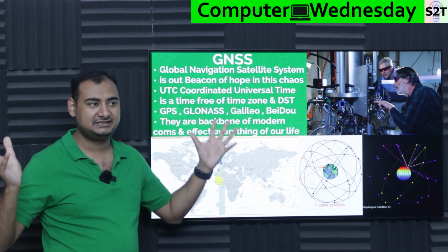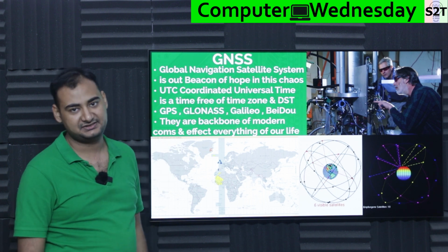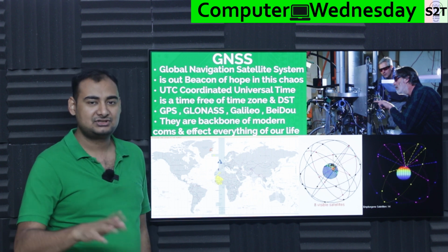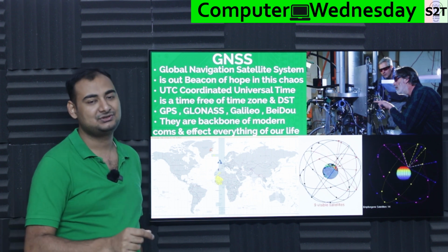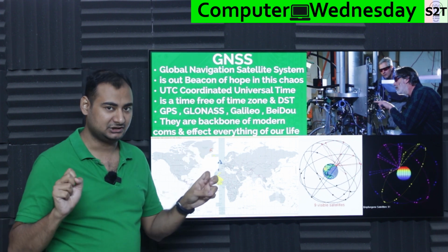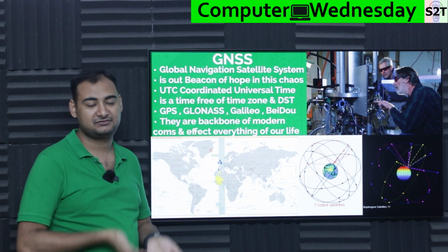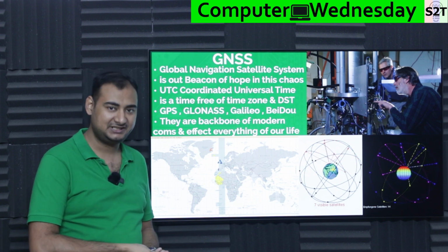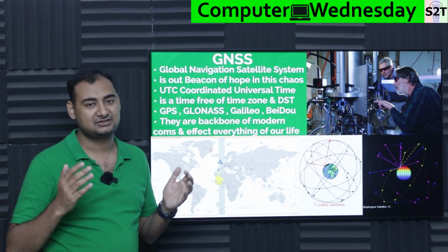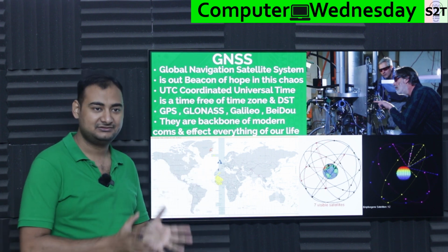So how does humanity deal with this? Well, we introduced GNSS, the Global Navigation Satellite System. Now, when we talk about a satellite navigation system, we think about it telling your position. Well, position is a side effect of time. If you know the position, you have to figure out how you are calculating it. You are calculating what we call trilateration, meaning you take 3 satellites minimum and you draw spheres out of them. How do you draw spheres out of them? You take the constant of light speed and then you calculate the time. That's why I said every satellite navigation system is just a super duper hyper fancy clock, which is very reliable. So that's how humanity works reliably.